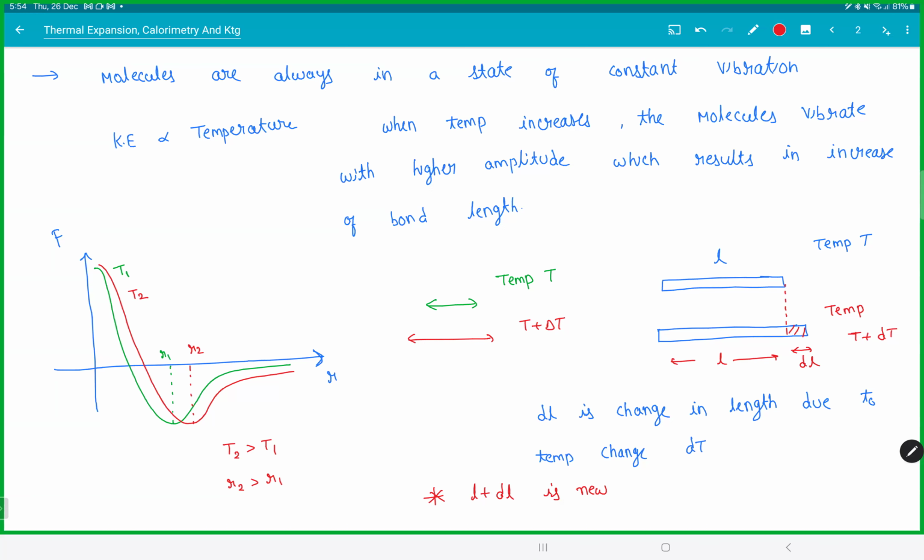Getting the difference? So in the same way, when you increase the temperature, the molecules are pushing each other and they automatically adjust and get this new length so that there is no stress between them. So this would be the new natural length at the temperature T plus dT. So when you say natural length, it means a state where you don't have any stress.